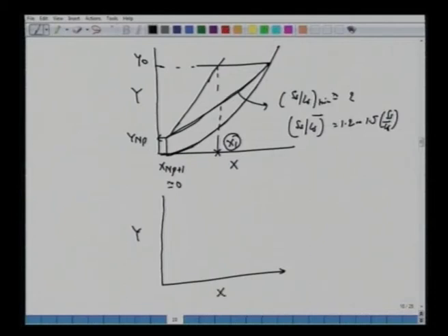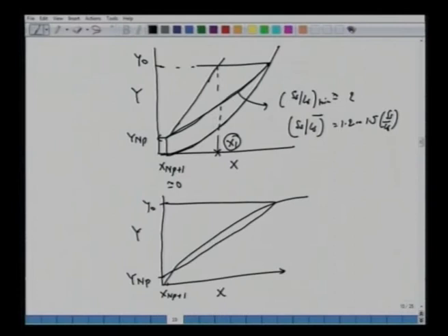Let's say we have an isotherm that is concave downward. Then this is y0, and this is a very small amount here, x_{p+1}, and we are treating this feed till y_p. If we draw this line here, then this SS over LS will give us some amount of adsorbent required, but you have to be careful that there is a possibility of things becoming tangent.